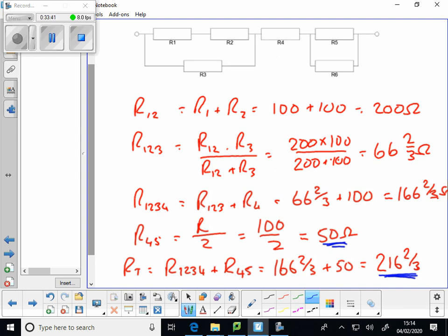And this parallel resistance is less than either of the two resistances that are in parallel together, 100 and 200. Just be careful. You've got to isolate that parallel bit to take it off. It's not the overall total, because that's the total of the combination.